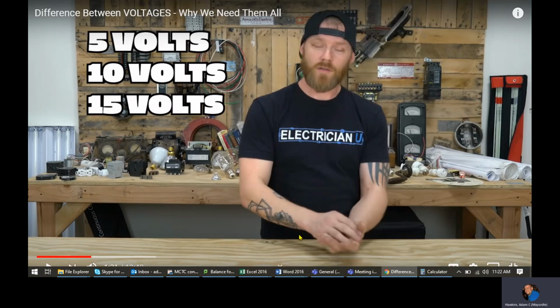I will chime in here and say a lot of our systems, especially larger commercial systems, can use different types of communication to their stats, and that's what he's referring to here, where they're sometimes even using DC. A lot of times you'll see on the back of a controller or a stat that's using some sort of building automation that it will say 0 to 10 volts DC.